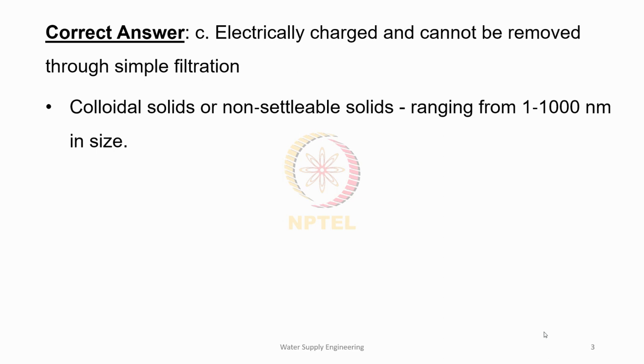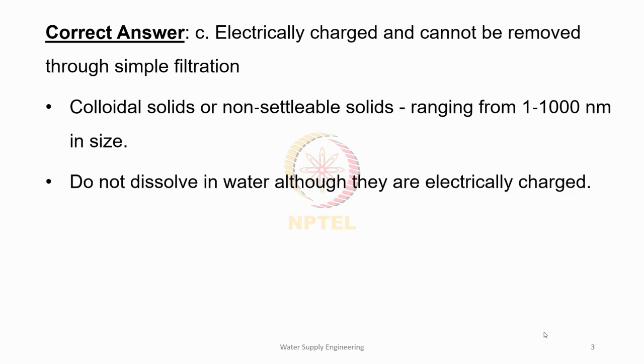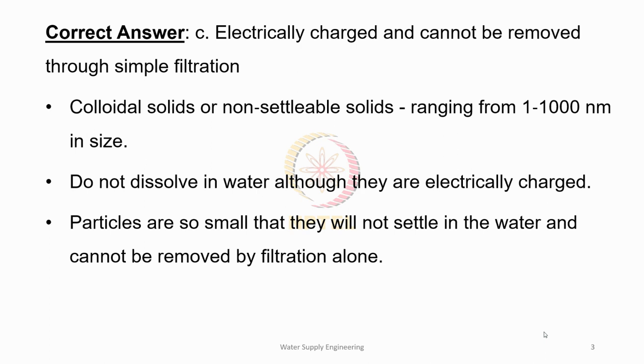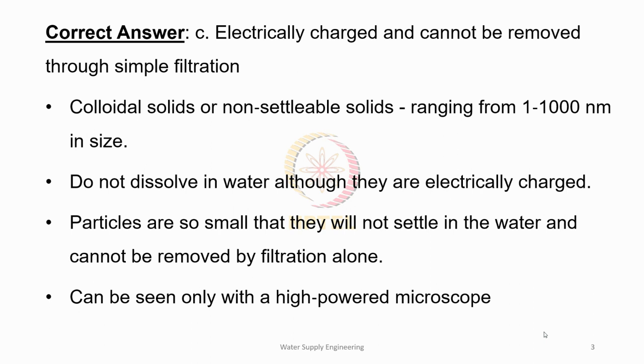Since they do not settle under the effect of gravitational force, they are also termed as non-settleable solids. Although they are electrically charged, they do not dissolve in water. Also, the particles are so small, that is in the 1 to 1000 nanometer range, they will not settle in the water and cannot be removed through simple filtration. These colloidal solid particles can be viewed only through high powered microscopes.